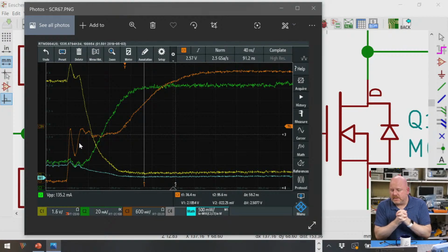Here are some tips when you design a board. Make sure you put in test points. In fact, this board has tons of test points, and I have some cool surface mount things that Peter from 1 Bit Squared recommended. It is recommended when you do a MOSFET design that you include test points for the gate and drain so that you can actually measure these effects to see what's happening.